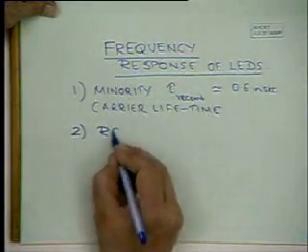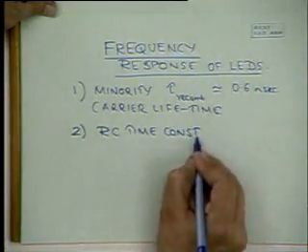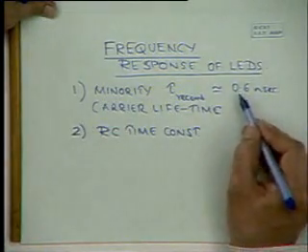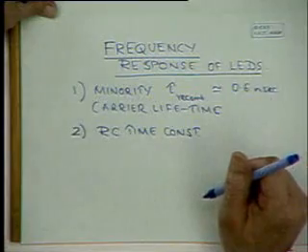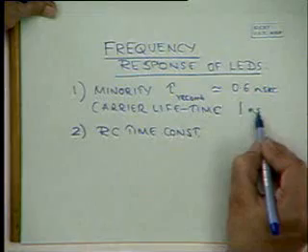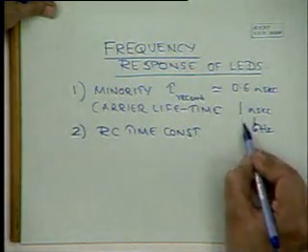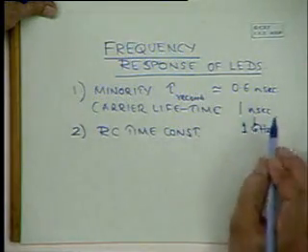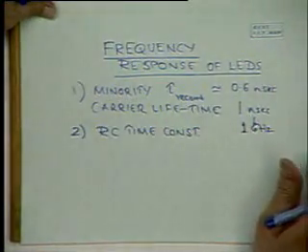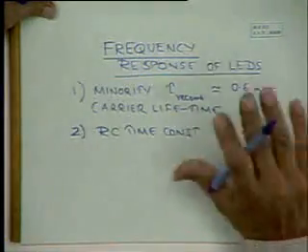And as in the case of all... Sorry, carrier lifetime is less, the high frequency response is high. Yeah, right. If you can intentionally reduce this recombination lifetime, then the frequency response will be higher. Remember, say, 1 nanosecond corresponds to 1 gigahertz. So that's quite high. Typically, almost something like this can be achieved. But there will obviously be a trade-off between power and frequency response.